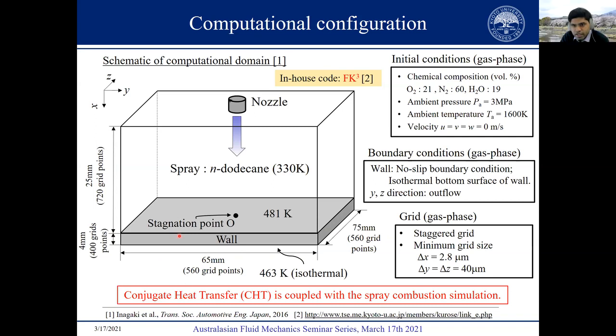For the time step value, we are taking the smallest of the two, because the CFD has its own CFL criterion, and your heat conduction problem has its own Fourier criterion for the time step value. So we take the smallest one and we advance the solutions together using the smallest value. Okay, yeah, thanks. Thank you.